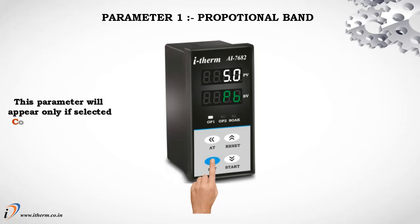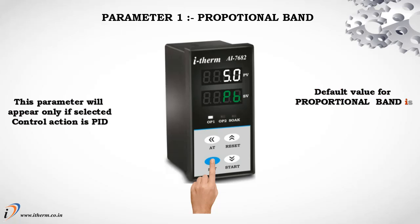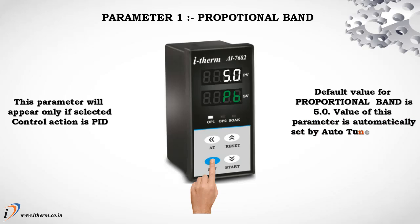Parameter 1, Proportional Band. This parameter will appear only if selected control action is PID. Default value for proportional band is 5.0. Value of this parameter is automatically set by auto-tune function.